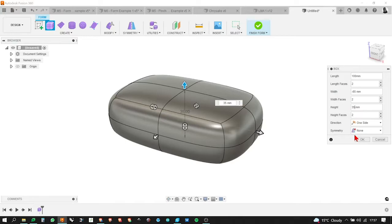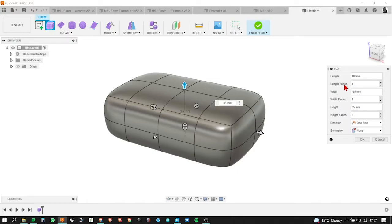One of the things that we can do is subdivide it. So you can see it's already subdivided to some degree. It's got two length faces, so this face and this face. Two width faces, this face and this face, and two height faces. That's just the default. We can add more faces to our box if we want to. So say I might want to make it 4 length faces. And now it's subdivided along its length into 4 faces.